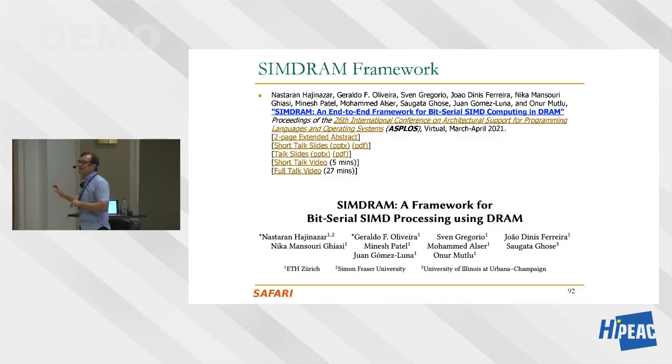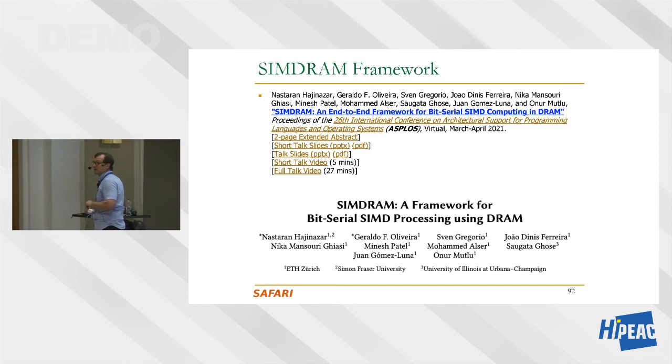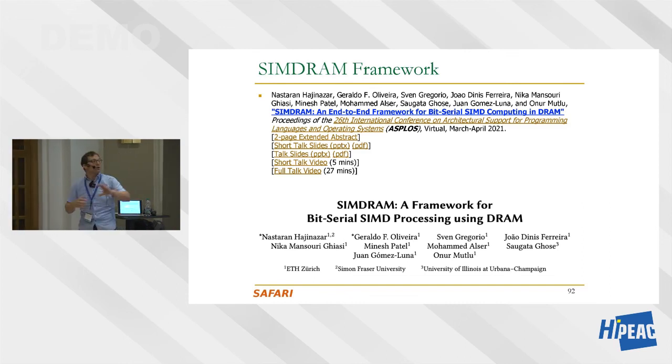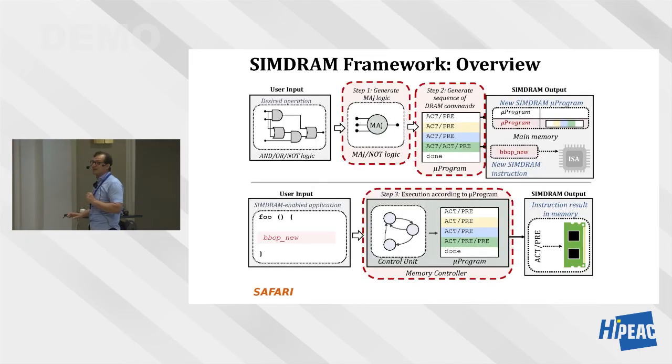Very quickly, as I said, you could actually do this for any operation. And this is what we did in this work. This is programmability. So always the question is, if you have a substrate like this, how do you program it? And we wanted to make it easy. And this is the framework that we developed. It looks complicated, but the user can now specify any desired operation. If they want to do a block bitwise operation, for example, convolution or matrix multiplication, etc., you can specify it using a hardware structure that looks like this, a circuit essentially, AND, OR, NOT logic.